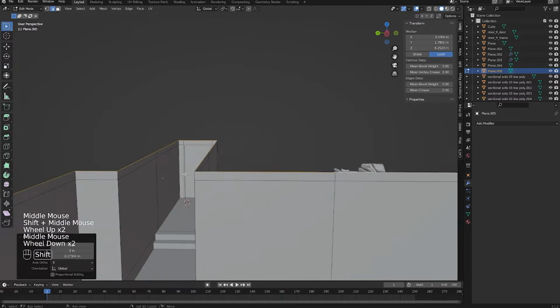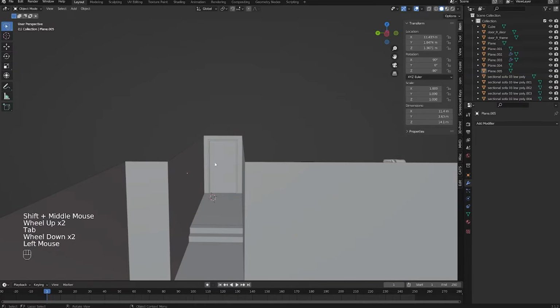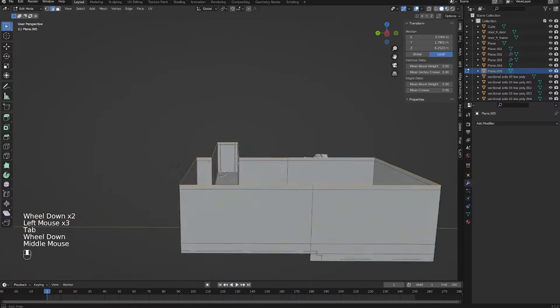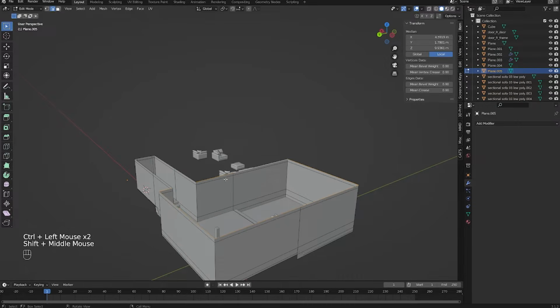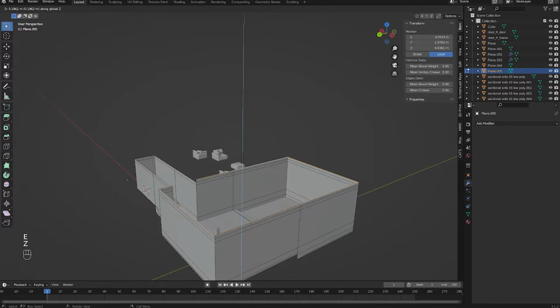It's just, you know, just trying to teach you some tools. And now, back in edit mode, let's deselect these edges. The way I do that is I hold Control and then I select the edges I don't want. And then I press E to extrude, and I'm going to lock through the Z axis.